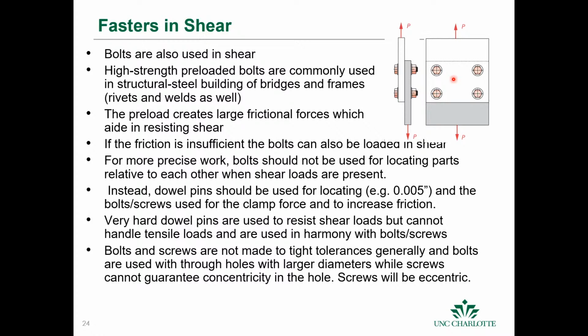Okay, so for example, tolerances of 5/1000ths of an inch. If you want to assemble a machine and you really need these tolerances because of your application, you can't have any slop, then you can install dowel pins, and then bolt it together, finish bolting it together.